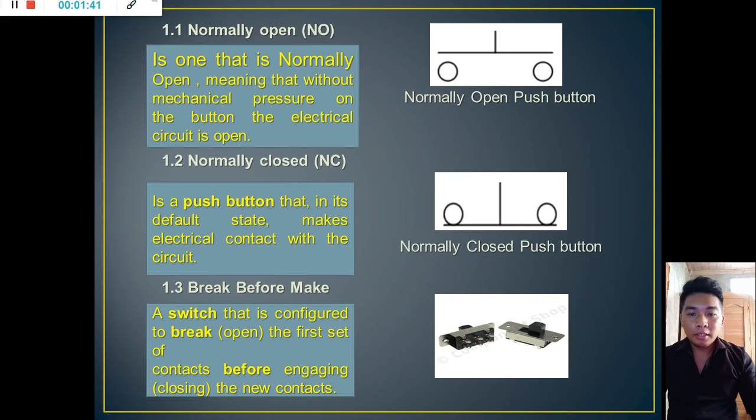So when you change the source, for example when it burns out, line 1 is on, which is the source. So you turn off line 1, and turn on line 2, which is the generator. So break before make.